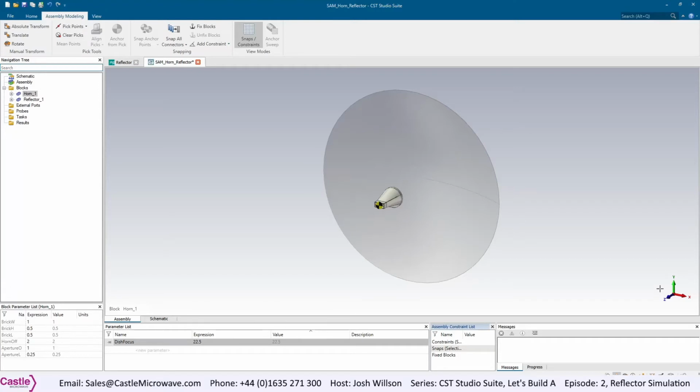There are 3 different approaches we could take to solving this simulation. We could do a full 3D time domain solver, which would require 3D discretization of the 3D space between the sender and reflector, and would result in billions of unknowns. We could do frequency domain analysis of the full structure using the integral equation solver, which would have a moderate runtime for the simulation, but only the surfaces will be discretized, and analysis is more challenging for a very complex feeder.